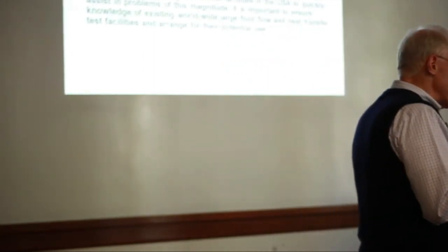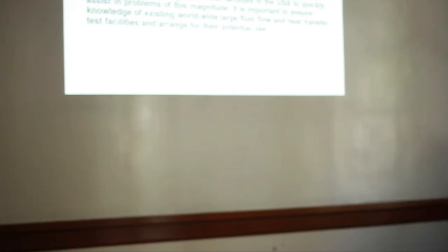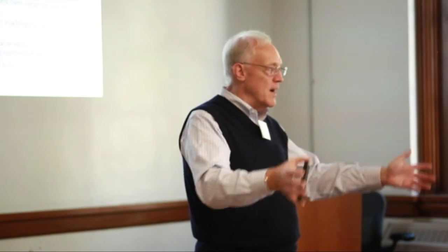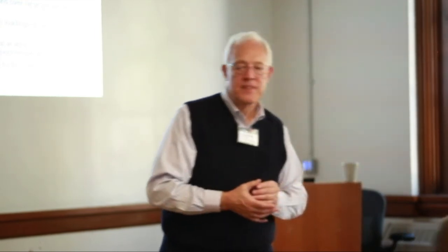Let me flip the question. I'm not at all expert in terms of your direct question, but let me flip on what we did. The way the operators were trained in the 70s and early 80s was basically event-based. I'm going to train you on an accident. The accident is a LOCA. What indications are you going to expect, and how are you going to respond? And that went on for all the things that might occur.